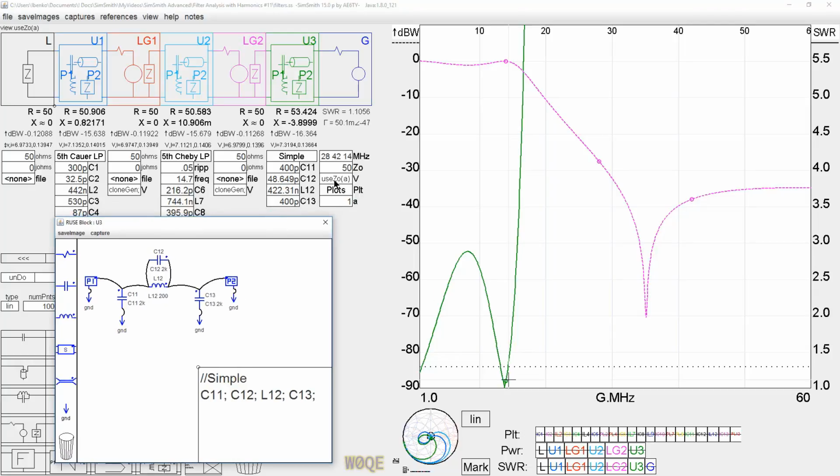and it's a standard Z0 output. The load is 50 ohms, so it's the best case here. And that's how the amplifiers are tested, by the way. They're not tested with a 3-to-1 SWR for measuring harmonics or anything. They're tested with a 50 ohm load.